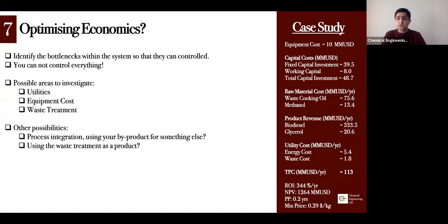The biggest example is water disposal. For example, I designed a process once where I had a fermentation reactor, and we were using water to dilute the process. After that, the same water then goes out. It was not being used anywhere. Instead, all that water had to be removed from the process. 90% of the waste treatment cost was in the water disposal cost. And there's no point in literally giving away all that water.